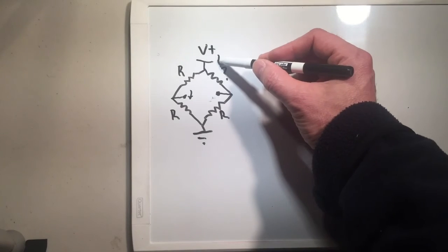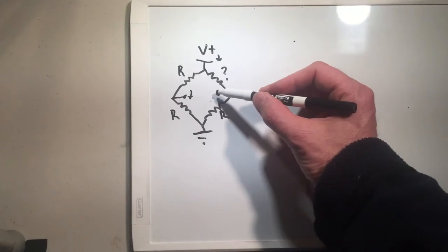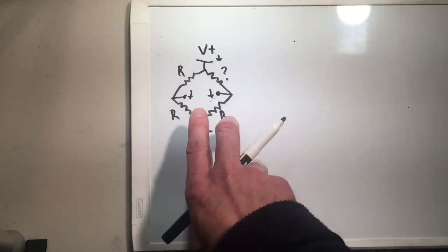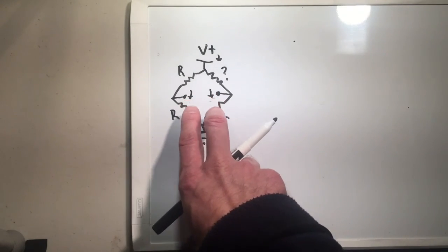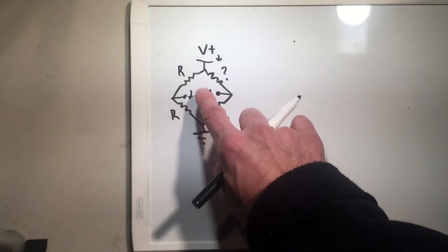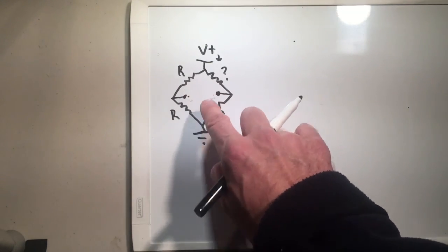Say, if the voltage here goes down a little bit, voltage at that node will go down, and the voltage at this node will go down. So if we're only measuring the difference between these two, then we're going to null out these effects right there. And to do that, we use something called a differential amplifier.